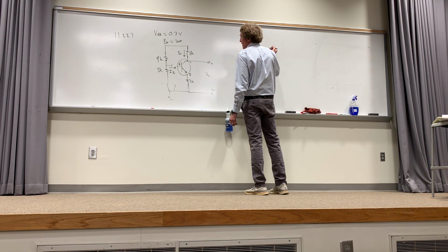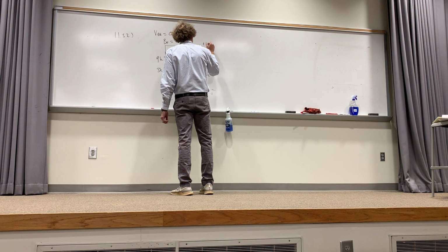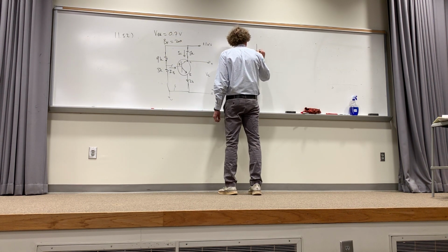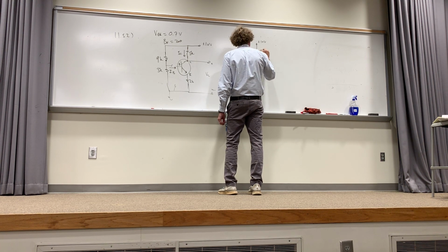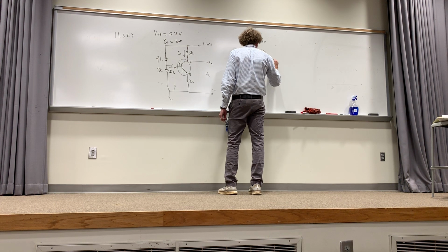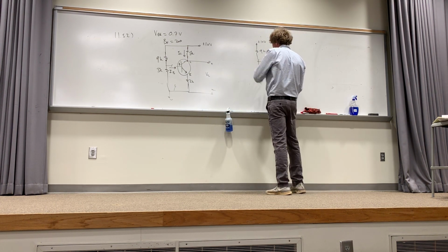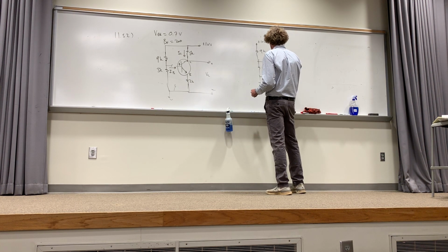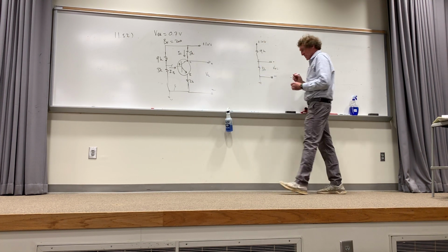I'm sorry I didn't put this here, this is 10 volts. So I have 10 volts here. I have 9K, and then I have 3K. That's grounded. And here's my output terminals that I'm going to hook something up to. So I want a Thevenin equivalent for that part of the circuit. This is going to be plus to minus V out. In this case, when there's nothing connected, it's called V open circuit, isn't it?